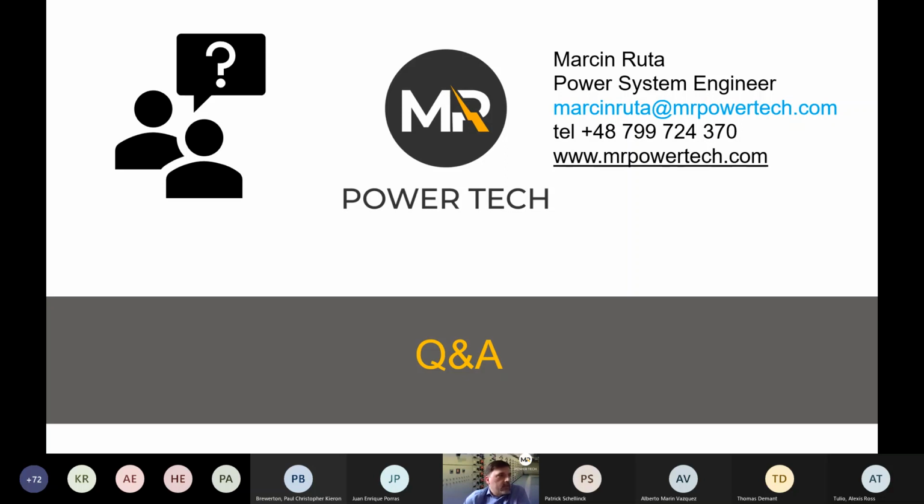Okay, so did you mention the program FabDoc for calculation? Is it because you have no experience, or do you not think it is appropriate? As far as I know, FabDoc doesn't do any arc flash calculation. But on the other hand, in my experience with low voltage calculation software, there's a big group of software that does not really handle arc flash well, and generally calculation if you have bigger systems.